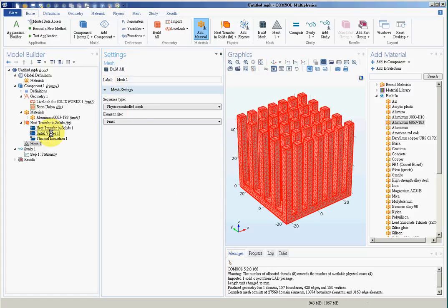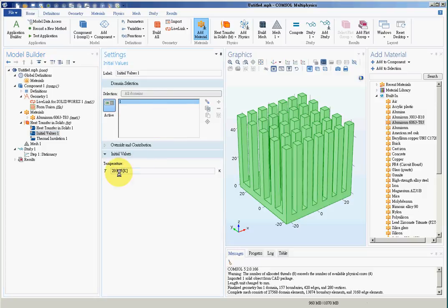Step 4. First of all, I can give it an initial temperature, which is really not important because in steady state thermal problems, the system will reach a thermal equilibrium where the temperature distribution is stabilized and the temperature shift is almost zero. So actually the initial temperature will not be important, but in this case it is designed here, so I'll give it 25 degrees C or 25 plus 273 degrees K.